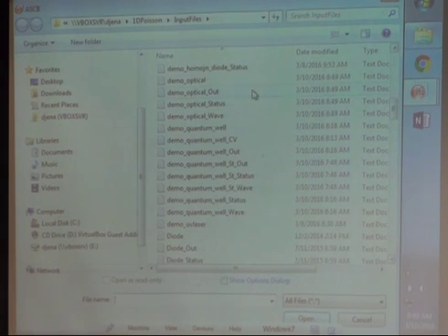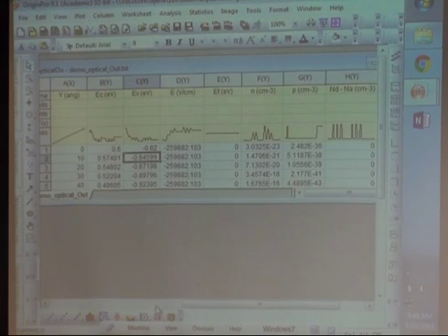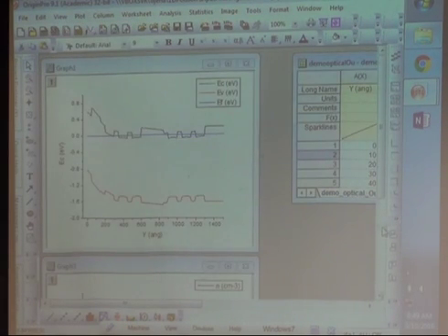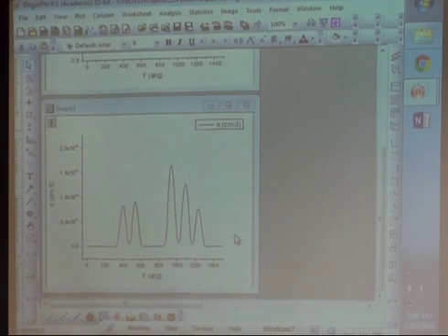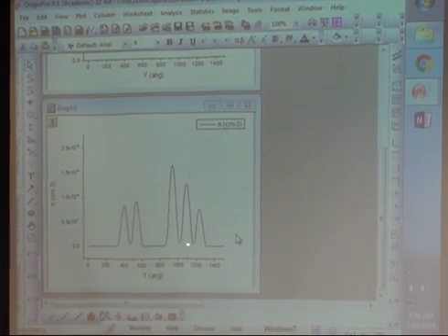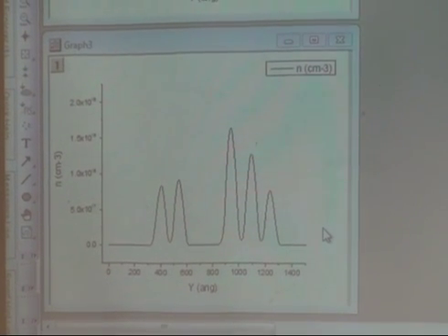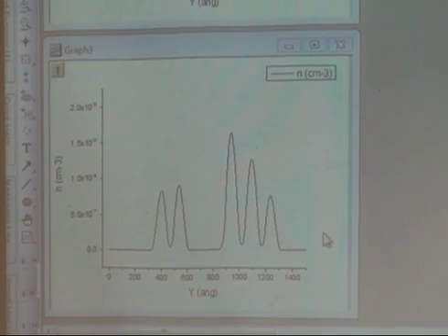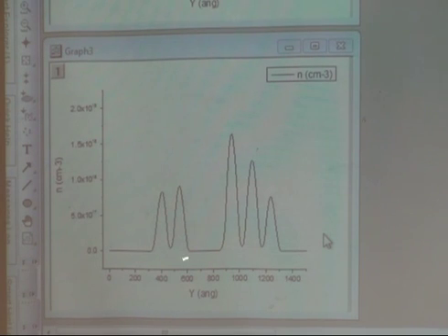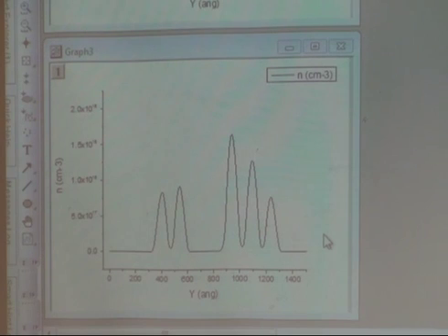Again, it will do what you expect it to do, but just to look at how the modified carrier density looks now, you can see it should really smoothen out, right? And it does. And the nice thing you see is now you can see that there is quite a bit of connection, electronically, between two wells. Because of the penetration of the wave function on both sides, these electron populations seem to have a strong connection, and they could potentially go across the barrier and all that kind of stuff. Okay, so